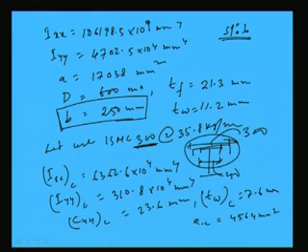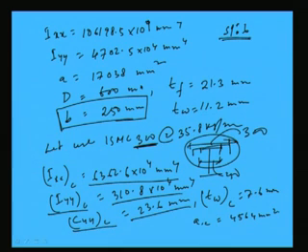Like Ixx of the channel, the moment of inertia about xx of the channel, 6362.6, and Iyy is 310.8 into 10 to the 4 millimeter to the 4, Cyy that is 23.6 mm, thickness of web is given 7.6 mm, and area of the channel is given 4564 millimeter square. So, with this now we have to calculate the neutral axis of the combined section, and the moment of inertia and other things of the combined section.